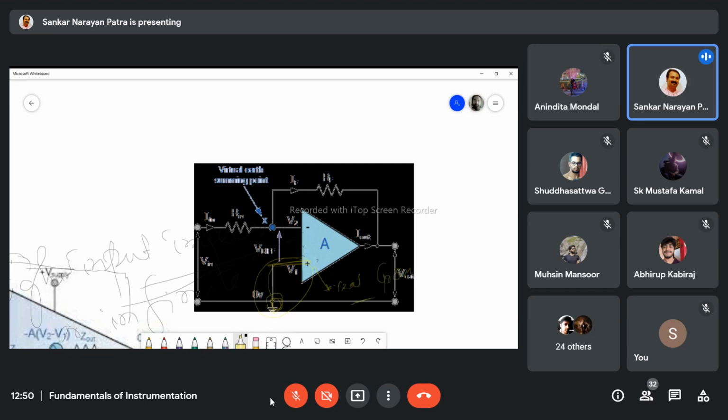And this is negative, and what happens here is that the input impedance is high. As the input impedance is high, no current tries to pass through this one, so it behaves like a ground, zero. But is it really connected to the ground? This one? No, sir. Directly, no. So what happens? It is also zero voltage due to this one being zero voltage, and it is called virtual ground.